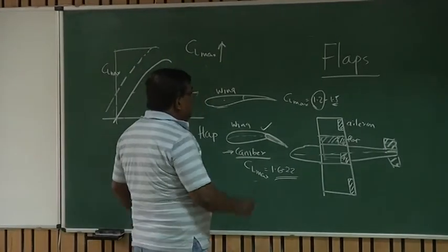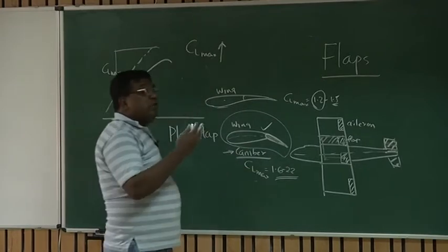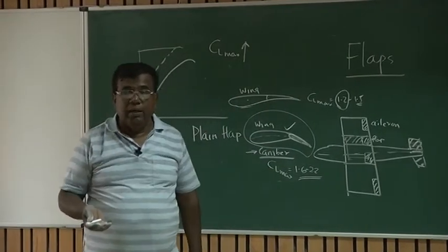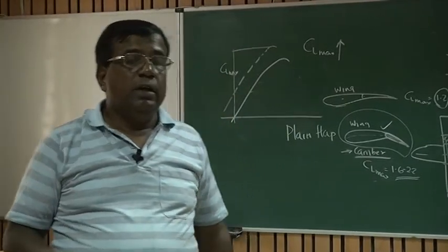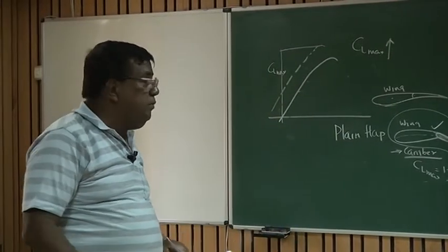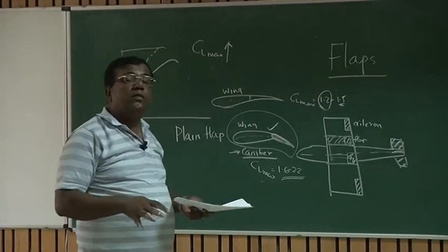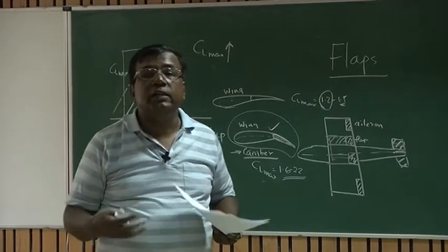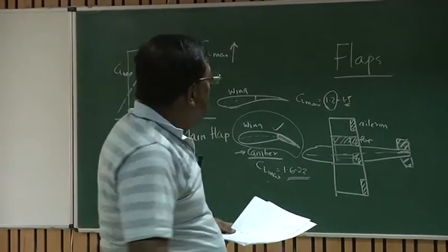So this is typically the principle of plain flap. Our Cessna 206 is having this plain flap, and I have demonstrated I can deflect that plain flap 10 degrees for takeoff and 20 degrees sometimes, but for full maximum flap deflection, I am sure that now I have touched the ground. That is primarily used for increasing the drag to reduce the touchdown distance. Okay, so this is plain flap.